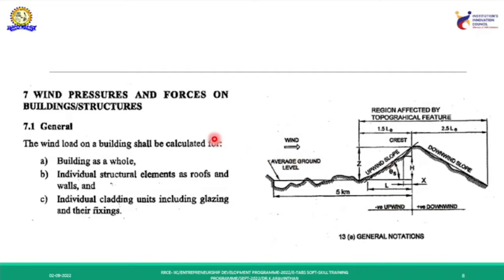When the wind is flowing in one direction, the terminology is that this side is called upwind, and the other side has what is called negative pressure. So in the coefficients, you will have plus values and minus values. A minus value means the negative pressure occurring in the direction of the wind. You can see here that on this portion the wind coefficient is taken as positive, and on the other side you have to take it as negative. That is why it is indicated as a downward slope.